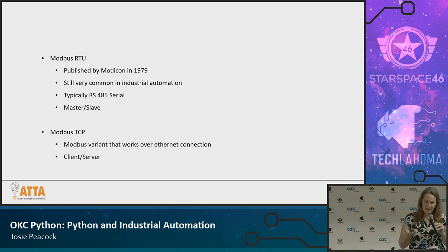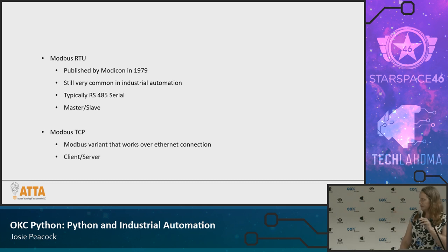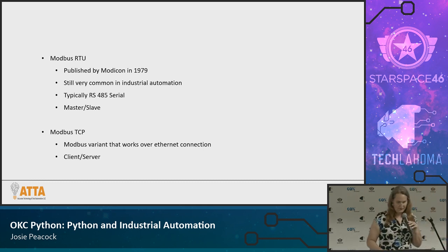I've worked with PySerial, I believe it is, which will do direct raw serial communication, and there is a Python library built on PySerial that will do the Modbus RTU. I've also worked with Modbus TCP, and it's like three lines of code. Suddenly you're reading and writing to a Modbus device. So it's pretty simple. Thoughts, questions?